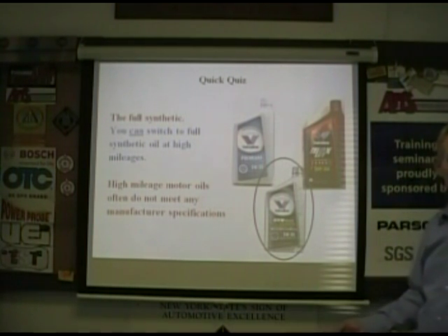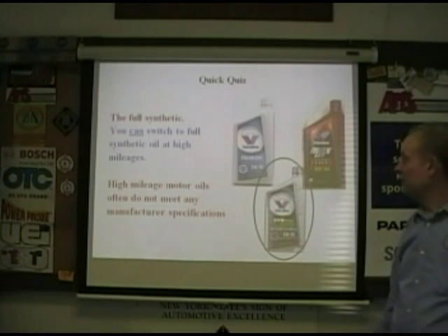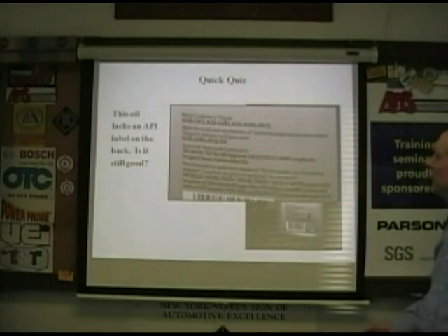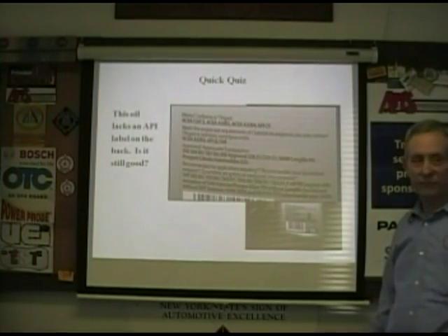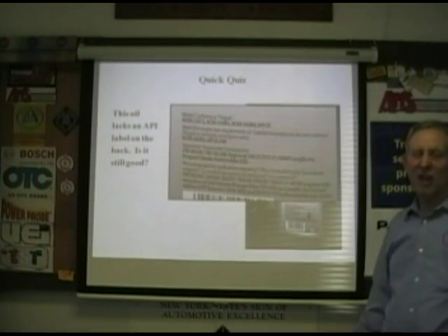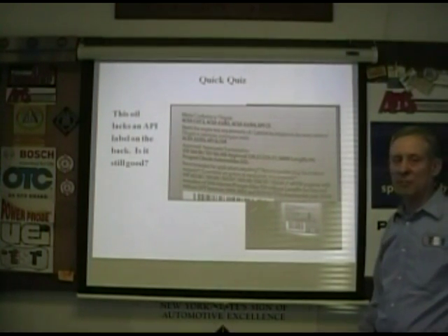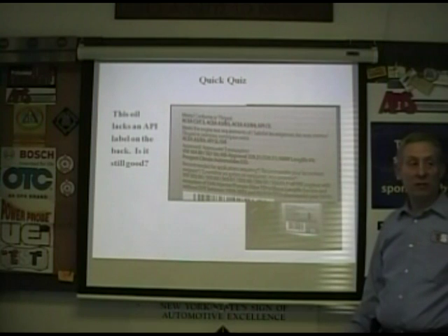I did that on my Jeep. I always changed the oil every 3,000 miles, and I used regular oil in the beginning, switched over probably the last 10,000, 20,000 miles to synthetic, and no problem, it doesn't leak. But the older cars, they had problems. Customers wanted to switch, they had seal problems. They had seal issues. I don't think that's true anymore, but only because the chemistry of things like seals has gotten more stable. I do get asked that question often.